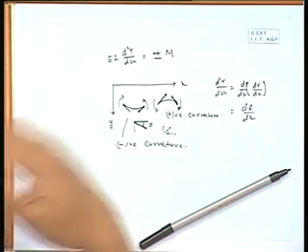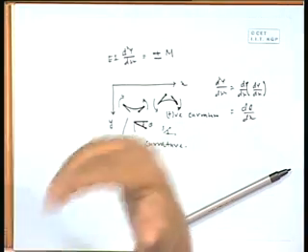So, normally last day we were trying to take sagging as positive, and we can go ahead with sagging as positive. So, at that level we will write moment with a minus sign. So, we have started with y, its first derivative is slope, and the second derivative with EI will be minus moment.